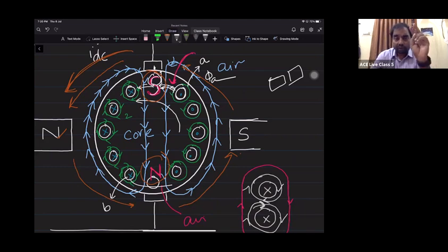Right. So before we leave for a break, I'm keeping 2 points to be noted. One: how many magnetic fields are required? Two. Why? There should be attraction and repulsion. Second: the relative speed between the two fields should be zero. Why? If the relative speed between the two fields is zero, the poles are stationary with respect to each other. When poles are stationary, there exists a continuous attraction and repulsion. Because of that, there is a continuous rotation.